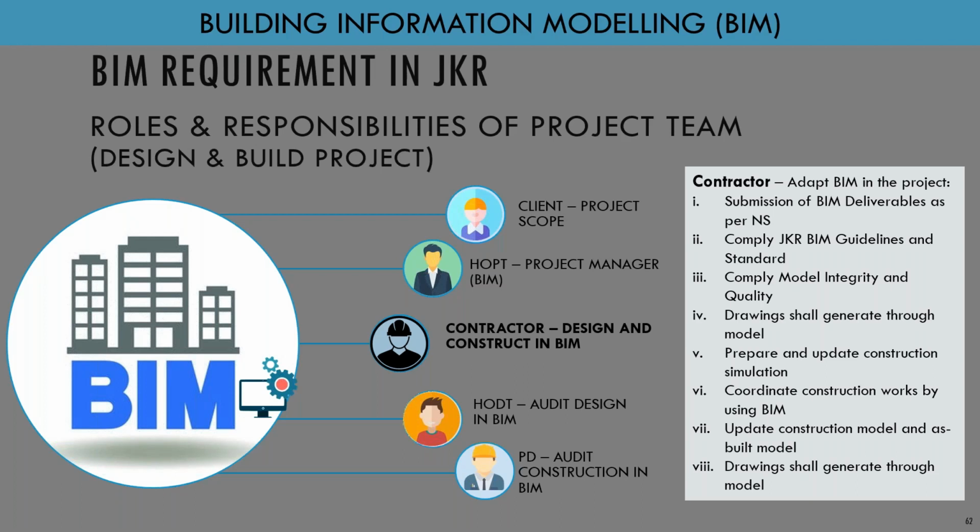So the contractor needs to adopt BIM in the project from the start. They need to submit all the BIM deliverables as per the need statement. They need to comply with the JKR BIM guidelines and standard, and comply with model integrity and quality. The drawings shall be generated through the model. They need to prepare and update the construction simulation, and coordinate construction works by using BIM. They need to update the construction model and asset model, and last but not least, all the drawings shall be generated through the model for the SBIT.